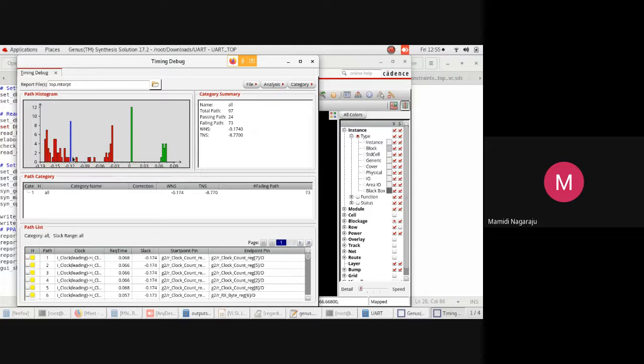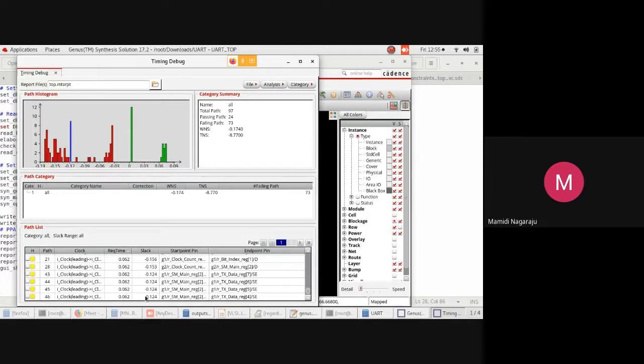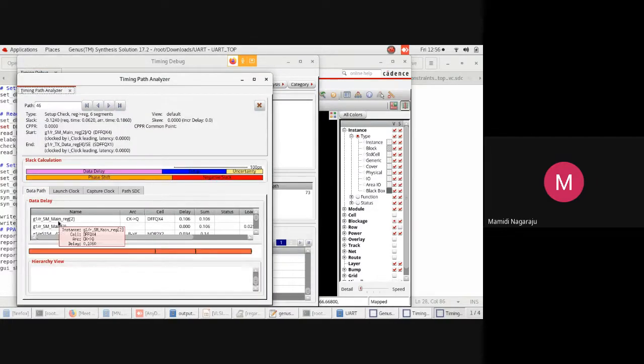So now you can see here 124 minimum and the required. So we'll check it. This is the path taking and we can visualize the path when we do the physical design. So now we can click on this to see what the path is traveling, where it is traveling. So it is data path, setup and negative slack, violation, uncertainty. So this is the color code you can see, and the path how it is traveling from clock to D flip flop, you can also see here with this.